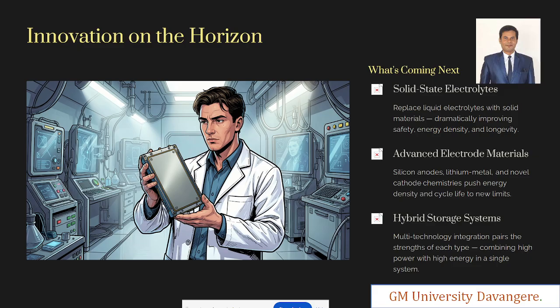And also if you see hybrid storage systems, we can have multiple technologies integrated, with the strength of each type, combining high power with high energy in a single system. That is what I was expecting, right? So we have to think about where we are compromising: sometimes we compromise on the energy, sometimes on the power. If we talk about batteries, as I told, in batteries you have to compromise on the power, but the energy will be more.